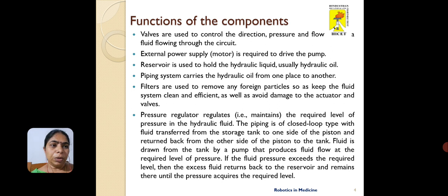Motor is required to drive the pump. A reservoir is used to hold the hydraulic liquid. Generally, the hydraulic liquid used is oil. Piping system carries the hydraulic oil from one place to another. Filters are used to remove any foreign particles from the fluid in order to keep the system clean and efficient, and also to avoid damage to the actuators and the valves.